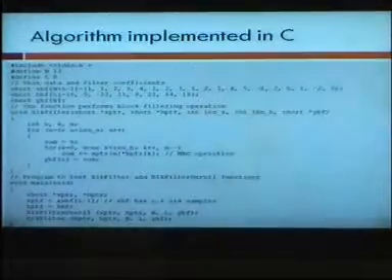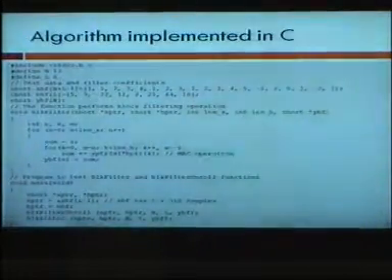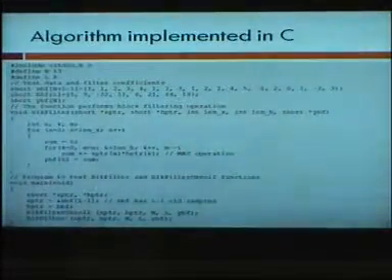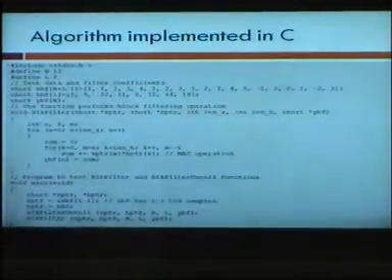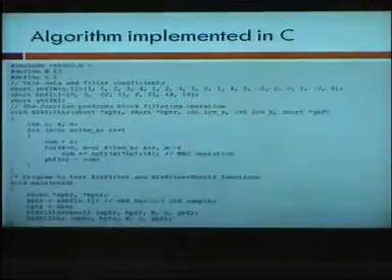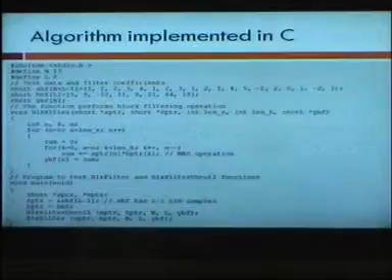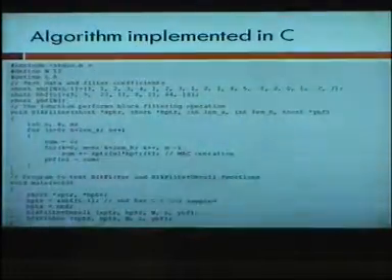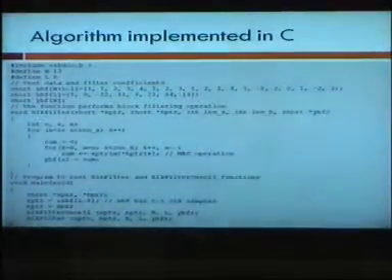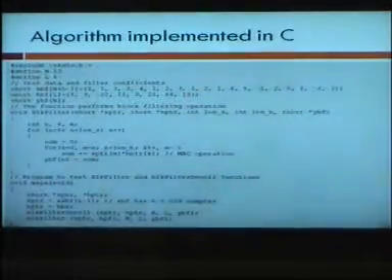So this is the overhead which you pay in software. Sometimes in signal processing applications, your requirements are such that you don't have these many extra cycles to waste. You just cannot call a function, and you don't want your processor to wait, maintaining the loop just to execute one instruction. So you are paying all this to execute one instruction. It's a huge overhead, perhaps 90% overhead and only 10% actual work in this piece of software.